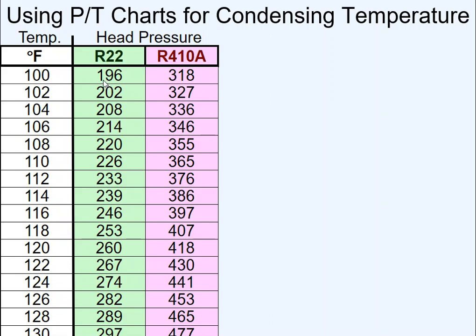So that's the biggest difference, at least for the technician, between these refrigerants. When R22 switched over to 410A, it was a huge switch because the pressures were so much different. We went from running like a 70-pound low side pressure and a 200-pound high side pressure to running 130 pounds on the low side and maybe 400 pounds on the high. To you that may not seem like anything, but for people who had done this for years and years and just went by the theory of, I just put my gauges on and this many pounds is what it's supposed to read,